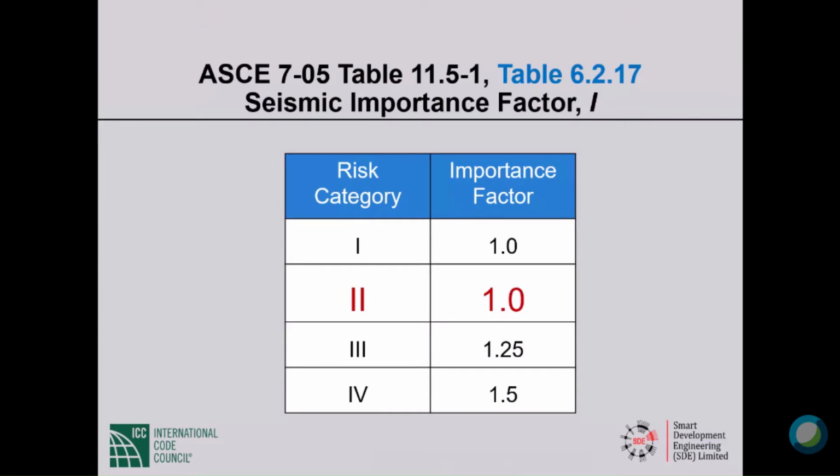Vertical combinations of structural systems. So in the design base shear equation, we had period, we had R, we also had I, importance factor I. These are the I values; they depend only on the occupancy category of the structure. This category I should have changed to occupancy category. However, no matter the time I spend and trouble I take, there are going to be mistakes in the slide sets.